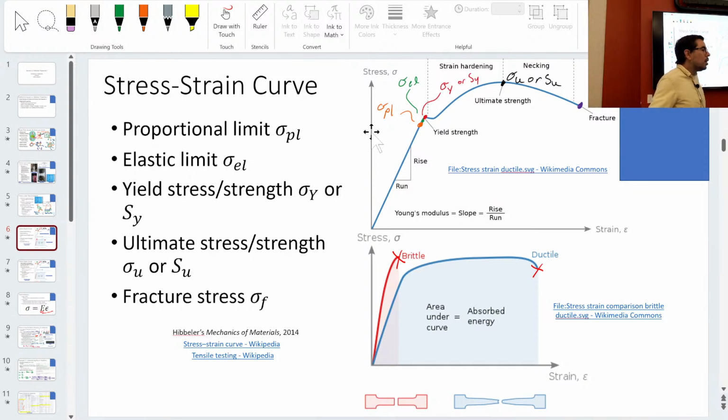Now, you do see something called strain hardening. So what's going on here? This is an interesting behavior. So I just said you get more bang for your buck. True and not true. For your sample, the force can be increasing, and then you get more measurable strain there. What's happening is, as you get to a certain point, you get necking.